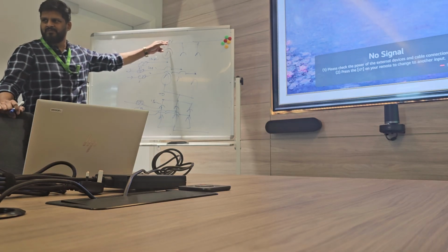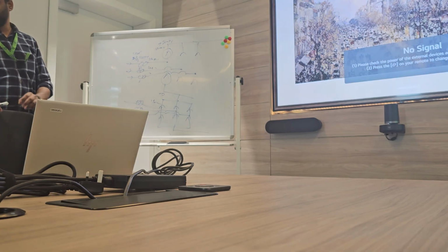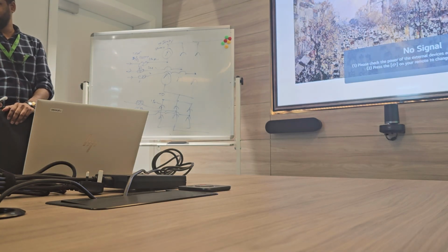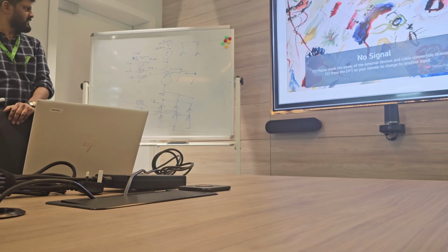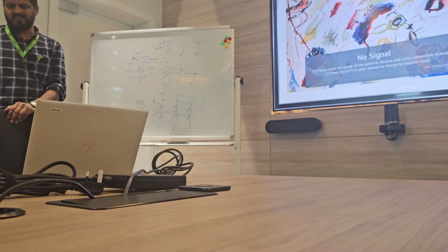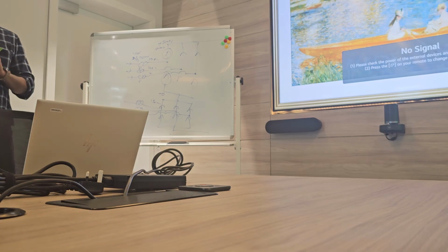Yes, this is my question. The first thing that came to my mind was, do we need a certain voltage near 500 for the IGBTs to work? But I asked many of my colleagues, they said no, this is only for isolation. So I wanted to ask you, what's the exact benefit of this transformer? The transformer provides isolation only, and transfers the power and connects the AC phases to the valves to make that connection arrangement.